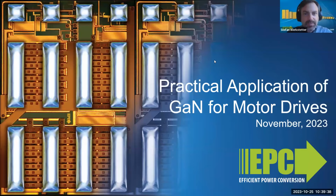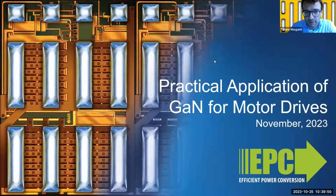Next question. When do you expect to offer eGaN with RDS(on) below 1 milliohm? We are working on it. We have first alpha samples of an 80 volt sub-milliohm device. So it's going to happen likely next year. Maybe it's not lower than 1 milliohm, but it's around 1 milliohm typical RDS(on). So it's a generation 6 power device.